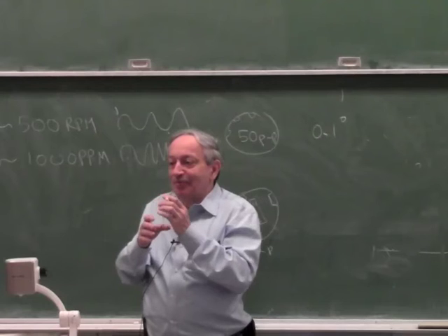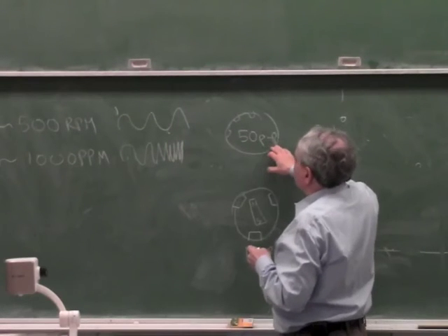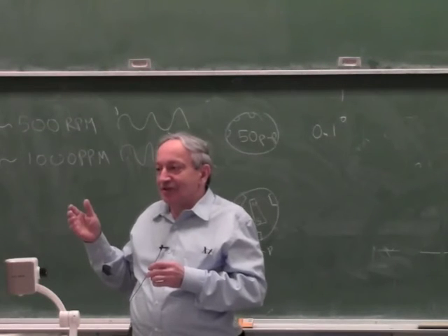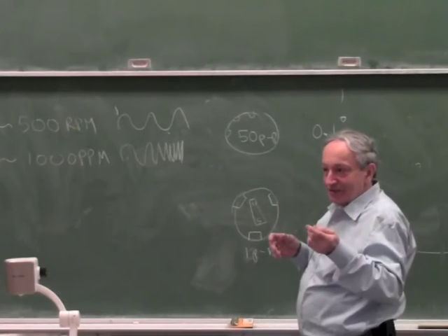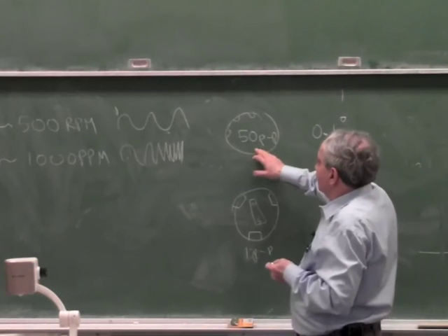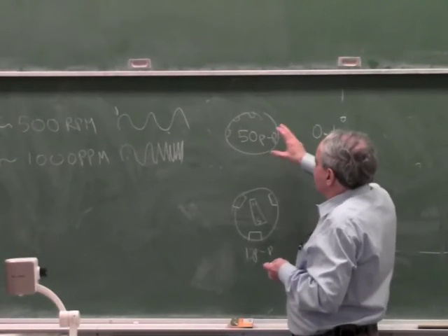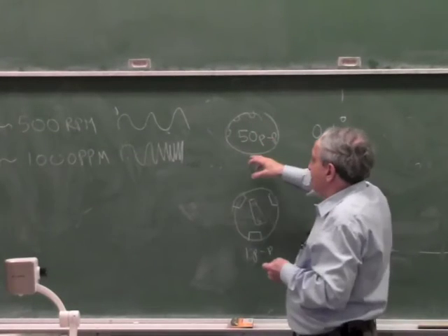Think of it as if you have a total of 50 pole pairs and the power angle can only reach 90 degrees, okay? So 90 degrees, that's a quarter of a cycle. You have to take one cycle and divide it by 4 to get 90 degrees, so it's 1/200th of a rotation.